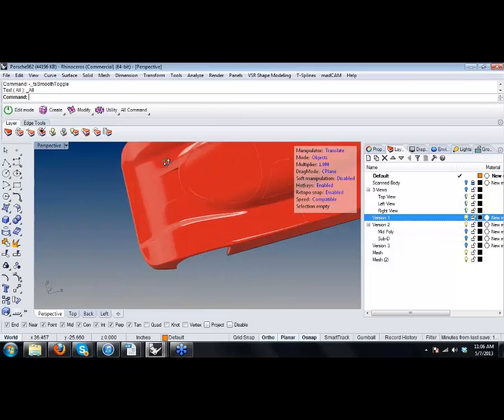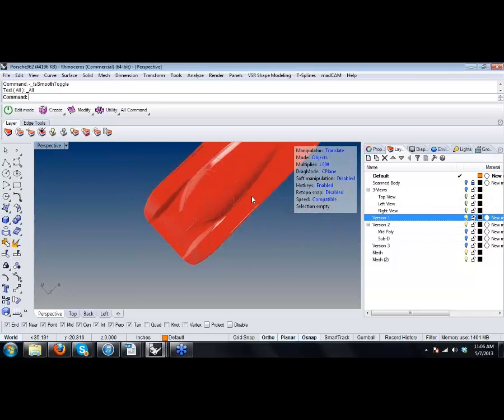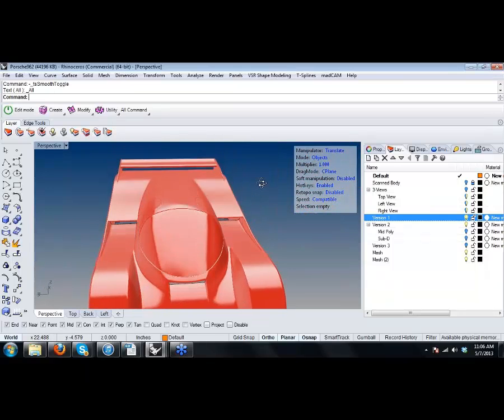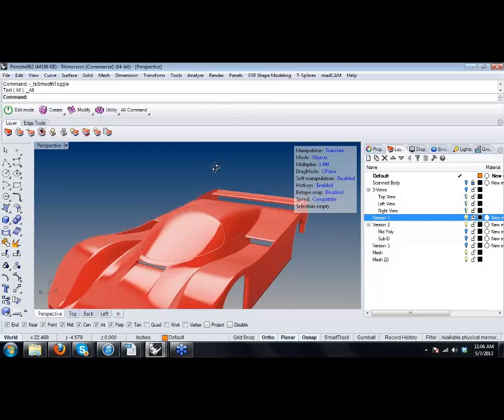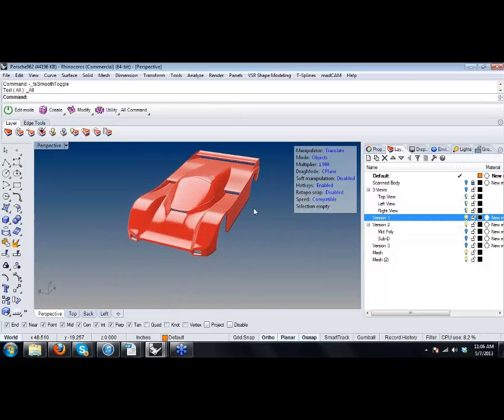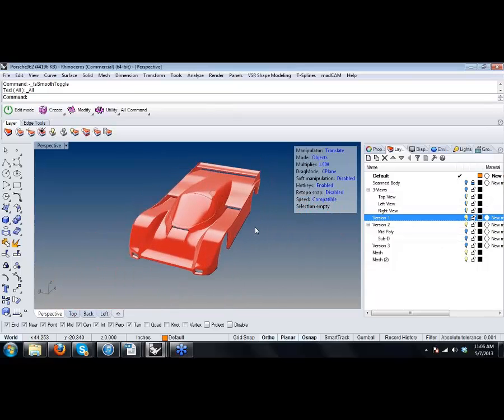So Sky, as far as how you approach modeling with T-Splines today, is it fair to say that you would consider, as a general rule of thumb, using T-Splines for the primary surfaces and then transitioning into NURBS for the secondary surfaces? Absolutely. I would completely agree with that. T-Splines are so good for those big macro shapes, and if you keep that T-Spline nice and simple, then you've got it nice and editable. Your life is much, much easier.